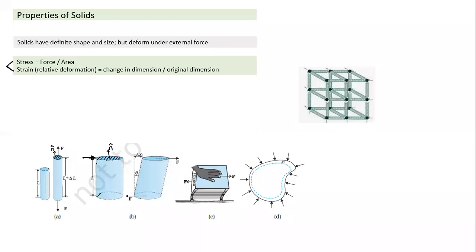And what kind of deformation takes place here? The deformation is like this. If you apply force like this, it may get deformed like this. The change in dimension and the original dimension are mutually perpendicular. Unlike the previous case, where delta and L are in the same direction, here the change in dimension and the original dimension we divide by are mutually perpendicular, and this becomes like an angle. Since they are mutually perpendicular and this being very small, theta is equal to delta x by this L here. This is shear. And shear deformation, you can also visualize as pushing a book here.